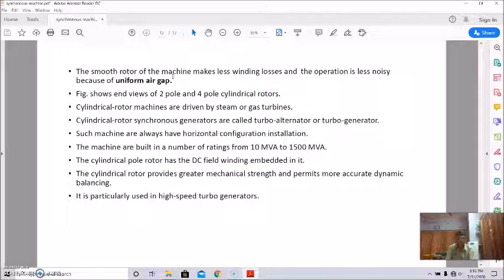So the high voltage armature winding, in stationary condition, will be free from vibration and centrifugal forces, and the output current can be taken from fixed terminals on the stationary armature without using slip-ring brushes.